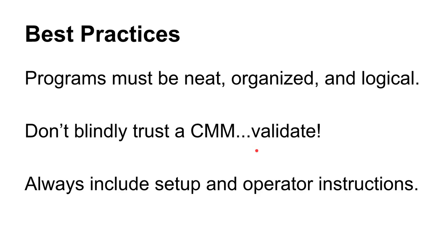And be careful of inspection sheets that say that a part is good. There is a very real tendency to take a report that comes out of a CMM that says that a part is in tolerance or out of tolerance, and that is generally the last word. That has to be validated ahead of time, though. You need to make sure that program, when it tells you that a part is in tolerance or the part is out of tolerance, that it really is. Do not just blindly trust a CMM. Be very careful of that.